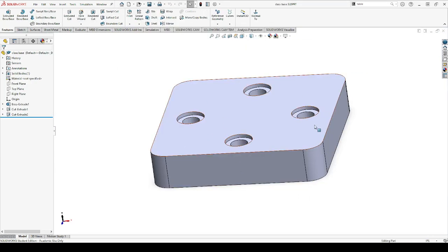And then this part here has a couple of properties for it. To find the properties, just come up here to the top where it says File Properties, or you can go to, I believe it's File and Properties right here as well. And in here we can add in a few things. I think the main one I always add it to is just Custom, and under Custom we have what they call Property Name.